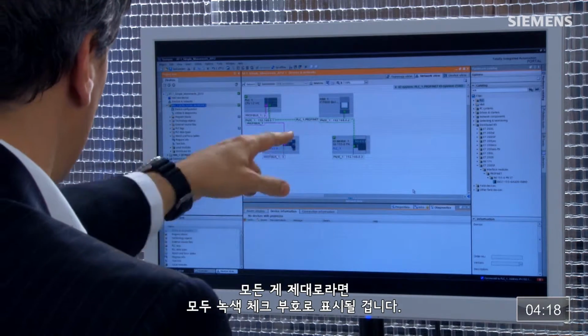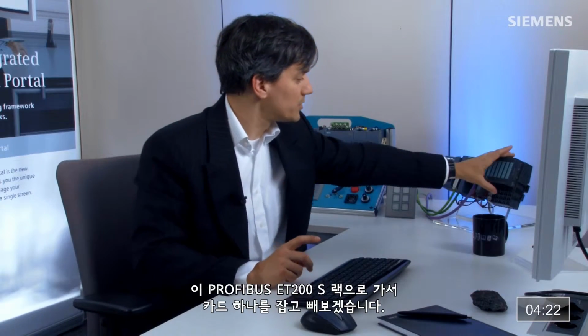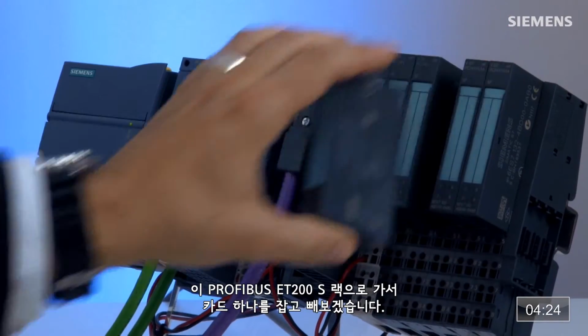And also, we'll have all the green check marks so we know all's well. If I come over to this Profibus E200S rack, grab a card and pull it out, you'll see I get a bunch of red LEDs all over the place.